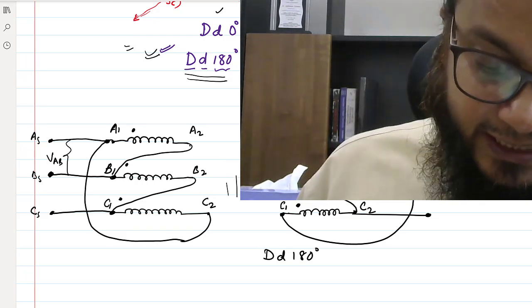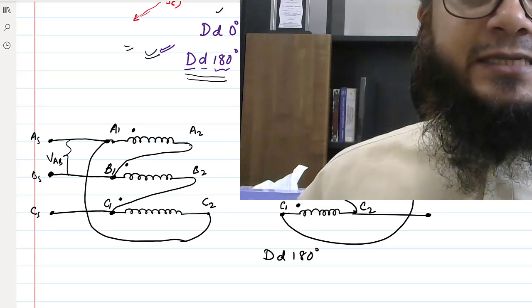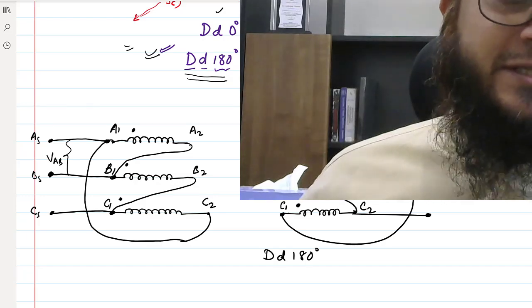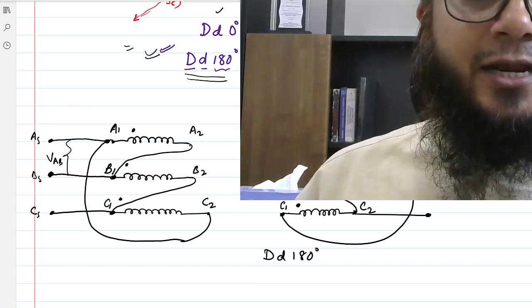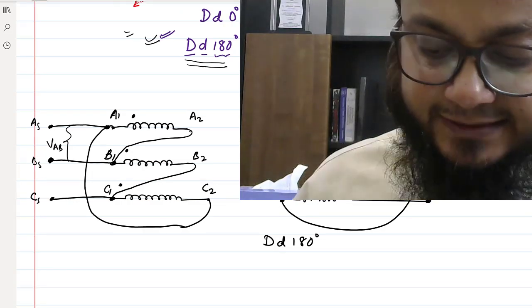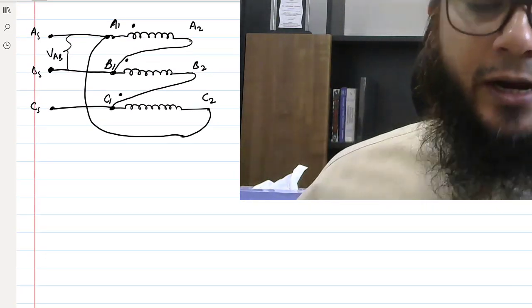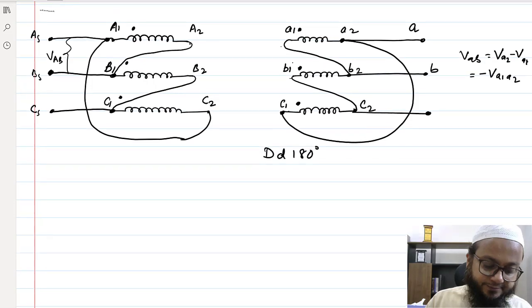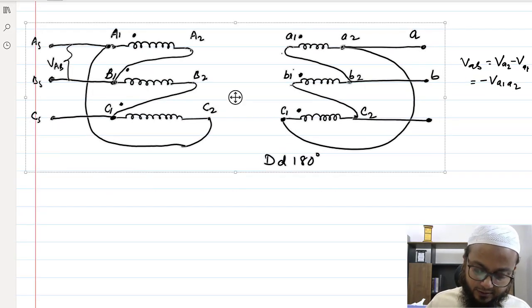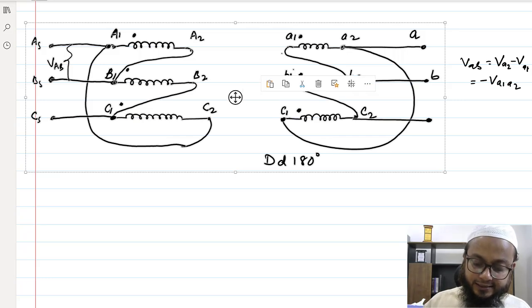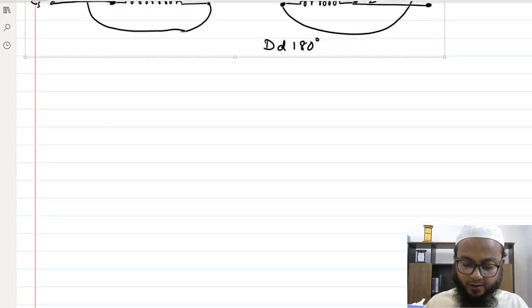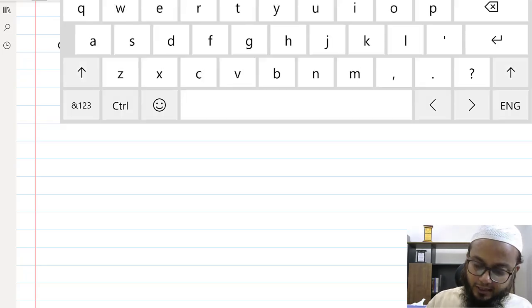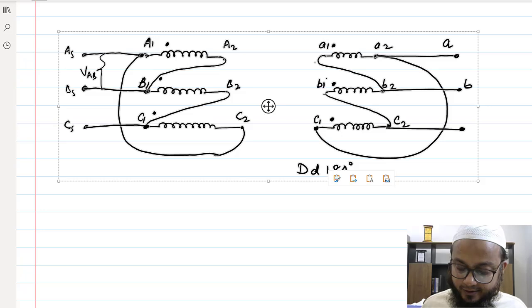Okay, but mind it, obviously these are single phase transformers I am just discussing, but this is equally valid for three phase transformers, any single unit three phase transformer. Now let's say someone says, no, I don't want to connect in this way, because this is just a matter of connecting in a circular way where the closed path is there, but that is not the case. Let's say someone does not take care of the dot and just connects as per his own wish and does not follow the dot conventions there. So see then what will happen.